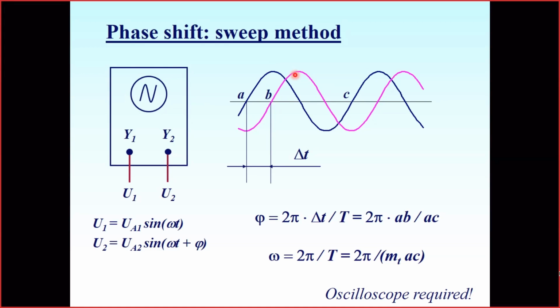An alternative way is to take the 0 point of the signal. We take the 0 line and look where our signal crosses the 0 point, and select one of the instances, either with a growing signal or with a falling signal. In my illustration, I took the points where the signal is growing and crosses 0.